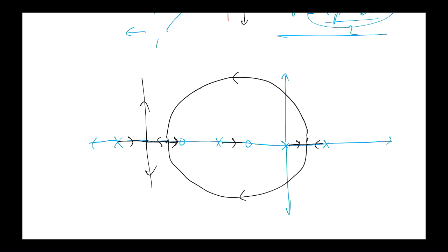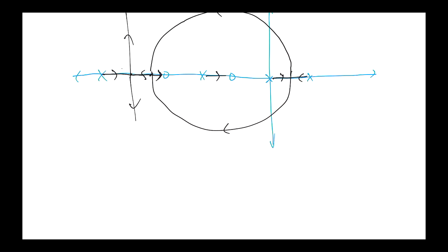Because the relative degree hasn't changed from the example above, right? Because for every pole that we've put in, we've put in a 0. Right, so for this pole we've put in that 0, for this pole we've put in that 0, so we haven't changed the relative degree, so we still end up with just 2 asymptotes. Now it doesn't necessarily do this and come back together again. It could end up doing this, and it really depends on the relative position of these different things, right? Now I can force it to do this by moving this really far to the left.